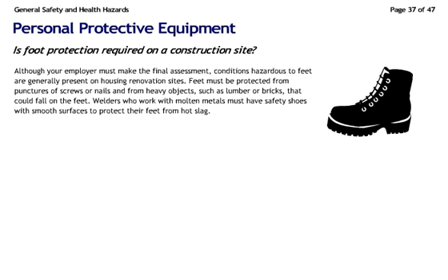Although your employer must make the final assessment, conditions hazardous to feet are generally present on housing renovation sites. Feet must be protected from punctures of screws or nails or from heavy objects such as lumber or bricks that could fall on the feet. Welders who work with molten metals must have safety shoes with smooth surfaces to protect their feet from hot slag.